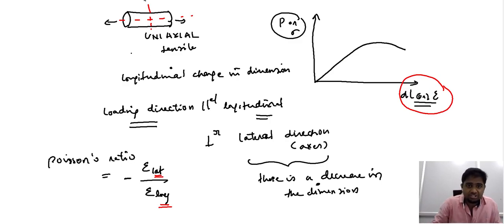By using this Poisson's ratio, we will now be able to describe both the lateral change in the dimension, or the lateral strain, and also the longitudinal strain, particularly when we are considering the ratios between the strains. The reason for expressing the response of a material in terms of strain is because the influence of the dimension on the response of the material is removed. So whatever we see when we discuss in terms of strain is exclusively the behavior of the material.